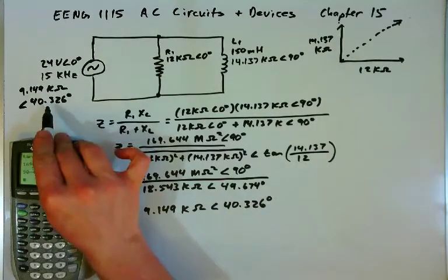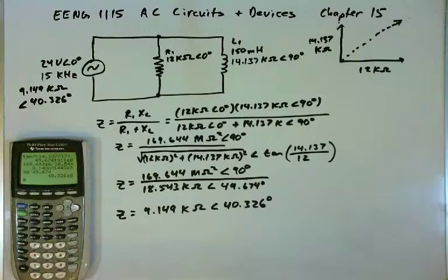So we've got the exact same answer that we had when we used the reciprocal of the sum of the reciprocals. And so I prefer this method. I think this is a little bit easier. I don't have to take the reciprocal of vectors and then add them together and then take the reciprocal again. The multiplication part here is a lot easier. We still do have an addition here, but overall I think this way is easier. The choice is yours as to which method you prefer.